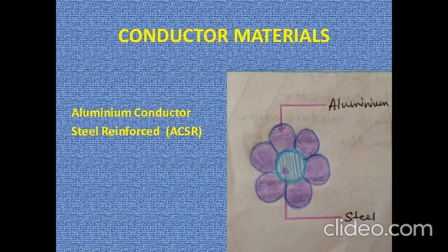Now in this figure, a steel cored aluminium conductor has one steel wire surrounded by 6 wires of aluminium. A steel cored aluminium conductor consists of a central core of galvanized steel wires surrounded by a number of aluminium strands. Usually, the diameter of both steel and aluminium wires is the same. The cross sections of the two metals are generally in the ratio of 1:6, but can be modified to 1:4 in order to get more tensile strength for the conductor. The result of this composite conductor is that the steel core takes the greater percentage of mechanical strength, while the aluminium strands carry the bulk of current.